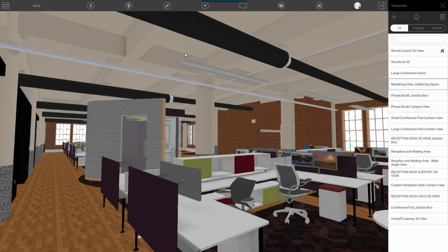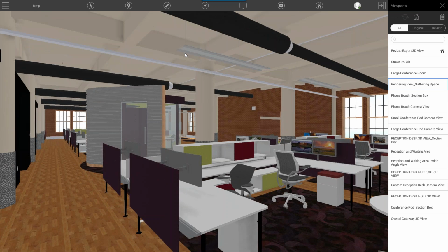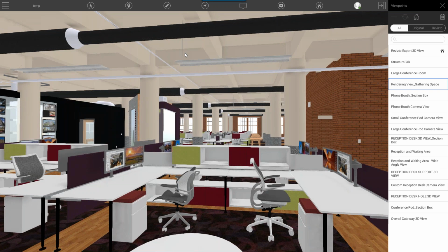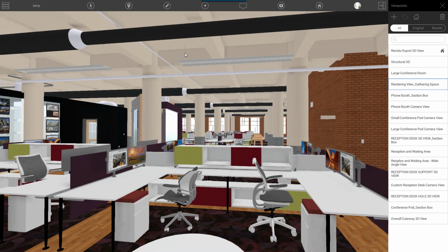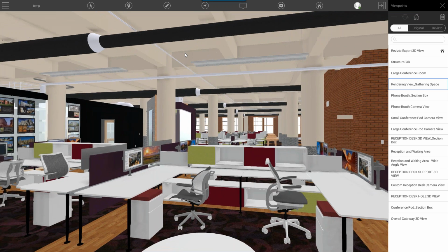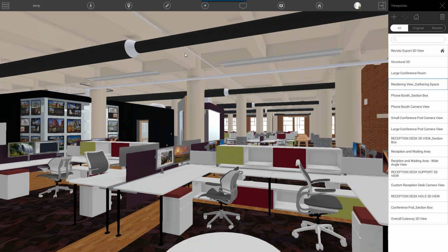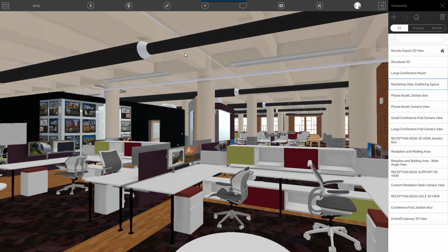So one thing I forgot to mention, in the Revit environment, was to point out the fact that there was a mechanical and electrical model being linked in to the architectural model. So all the information from those links is showing up here as well. You can see up above there's the fabric duct showing up and all of the LED light fixtures.